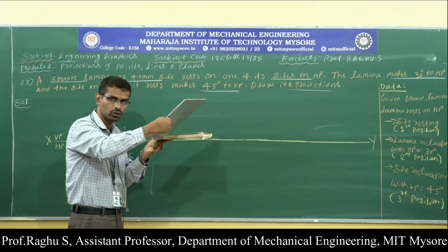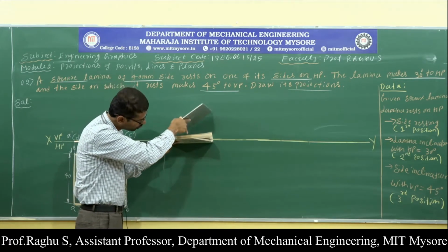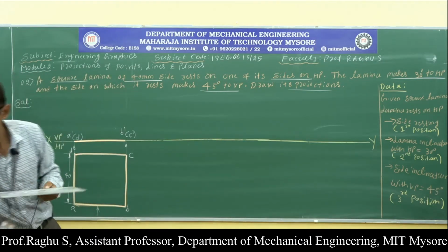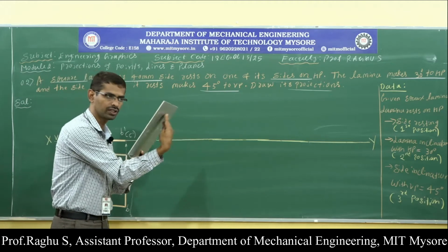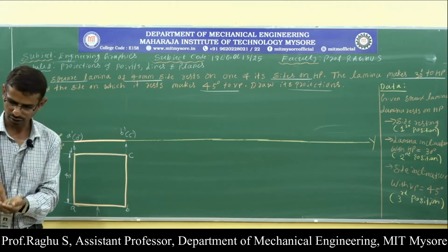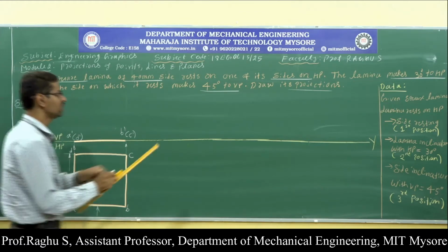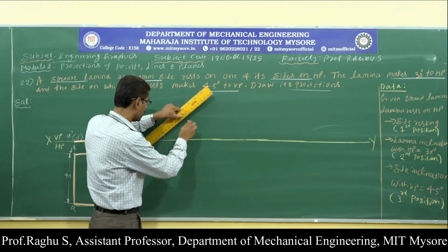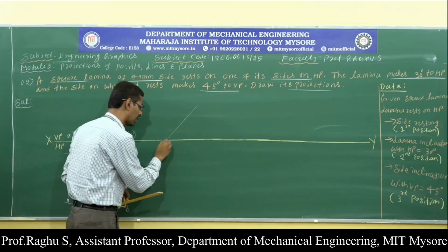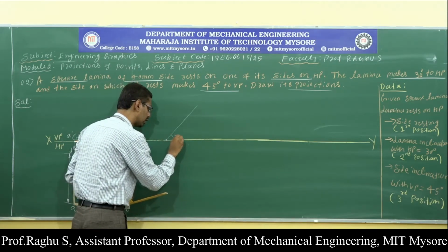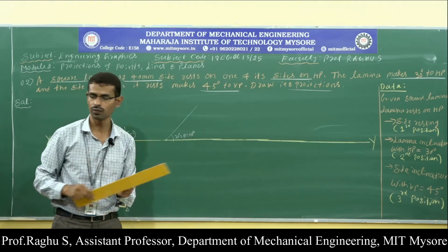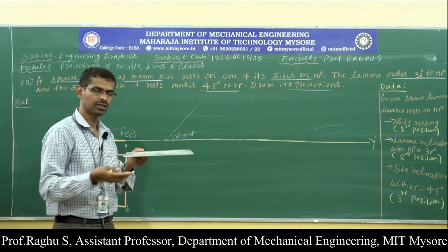In the front view. You are the observer. In the front view I am going to see this inclination, along this inclined line. Now to draw the second position, the given inclination is 30 degrees. The 30 degree inclination is visible in the front view. Take or draw a 30 degree line at any point on the XY line, that is theta with respect to HP. This inclination is visible in the front view. Already I have shown this is the HP, and the lamina.